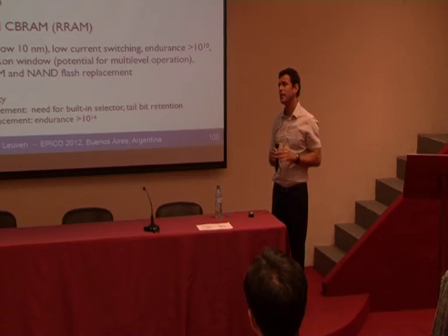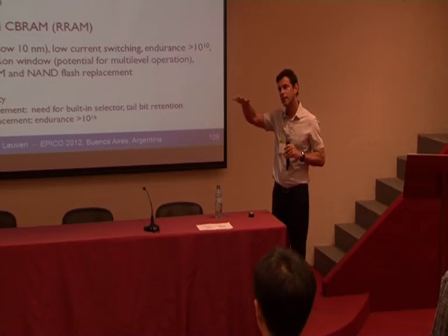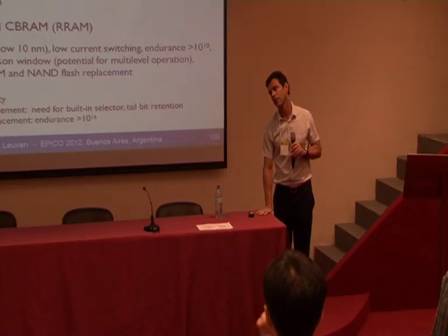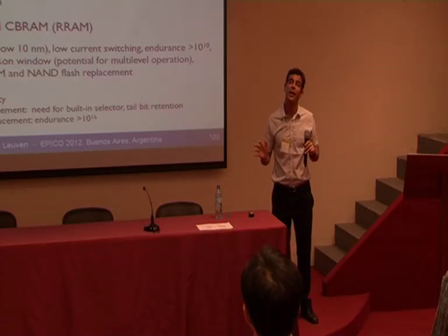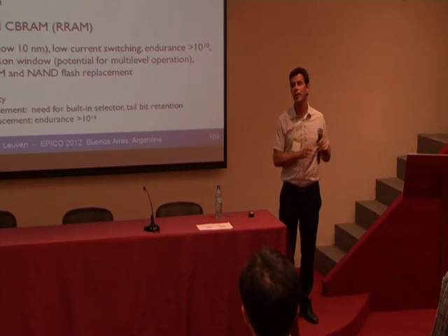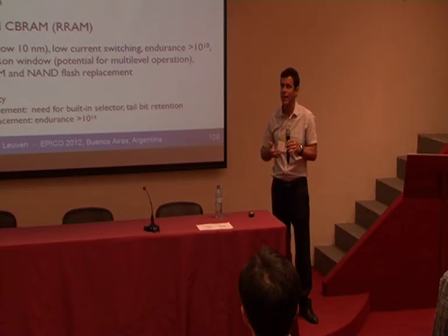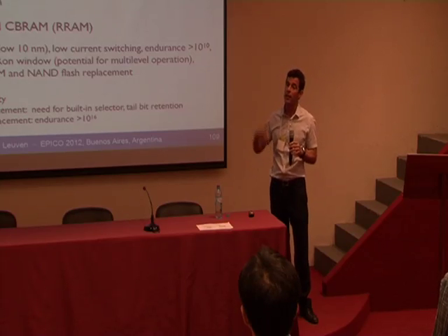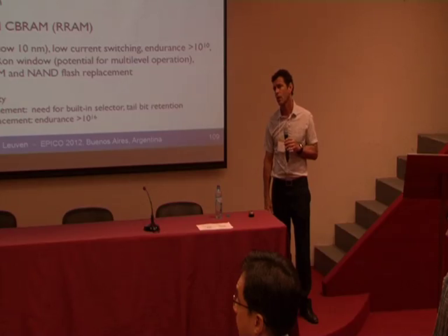So basically, the material itself has a temperature transition point, right? Yes. As I showed, which is 70 degrees C. You start at room temperature, you pass a current, you have Joule heating, it goes above 70, it switches. So we didn't find anything inconsistent with that. Some people argue it's an electrically driven phase transition. We have not seen evidence that you need to imply anything behind that.